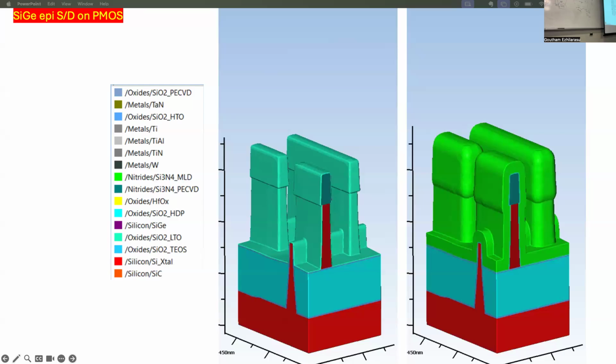But you see, it's perpendicular now, right? Yeah. And then you do the same thing. So first you do a lightly doped implant. How do you get it on the sides though? Because if you're doing an anisotropic etch from the top, right, then it would... No, an anisotropic etch is just from the top, right? It doesn't matter whether it is going this way or this way. It's still going to create a sidewall spacer.